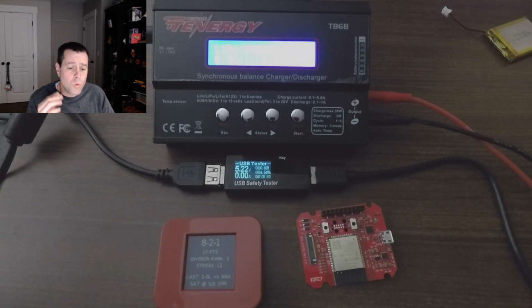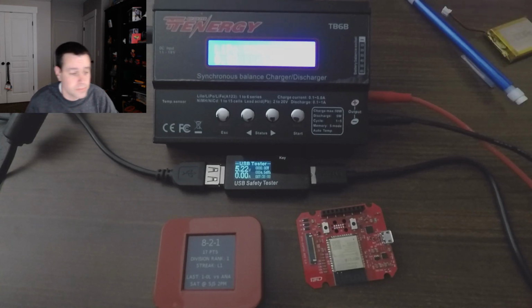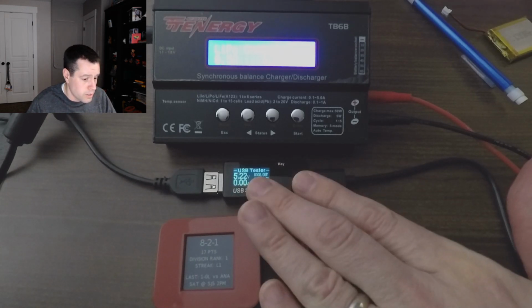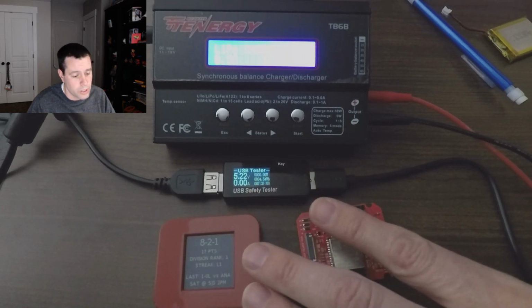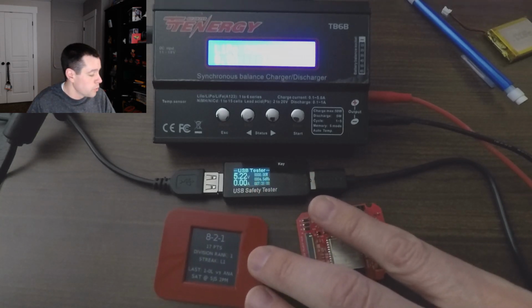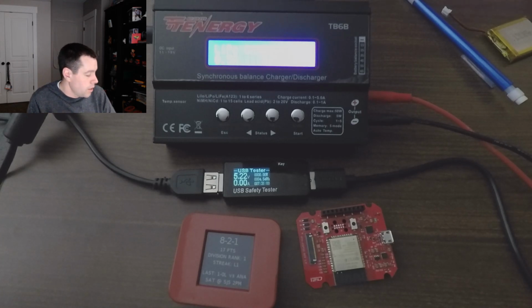But so what I'm hoping to accomplish today, and I do not know how far we're going to get on this, is I used this device here to determine that the charge circuitry was working correctly on our original hardware, making sure that this fast charge current is right around 180, 178.